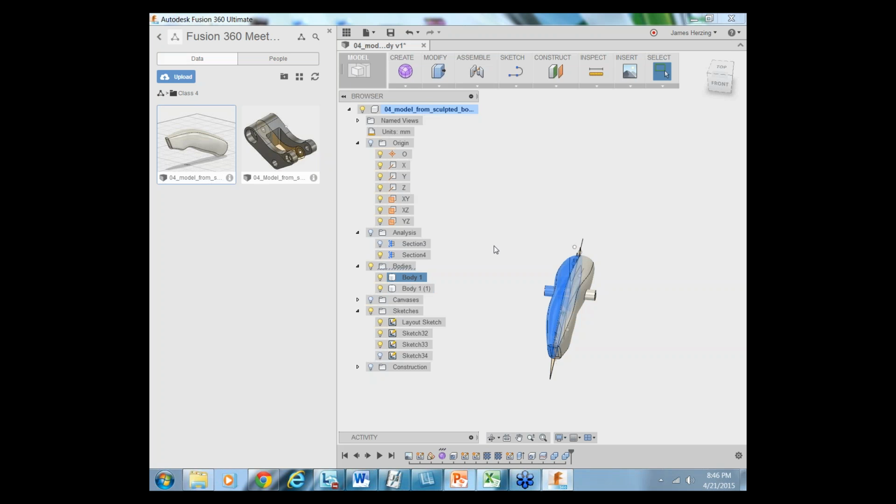So we just split stuff and made 4. We combined them and made 2 again. But instead of having the knife and the cylinder as the 2 bodies, we've now combined it so that it's half of a knife with half of a cylinder and another half of the knife with half of the cylinder. So what's the purpose of splitting and then combining them? If we were actually making the knife, it wouldn't be one solid body. I guess they kind of combine together and snap together in that fashion. But we're also going to then manipulate this cylinder in a different fashion to change our geometry, and it has to be combined in that fashion.